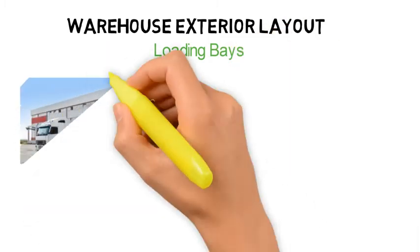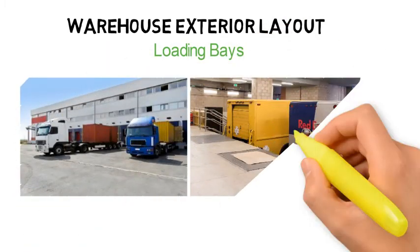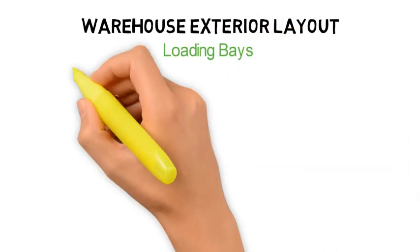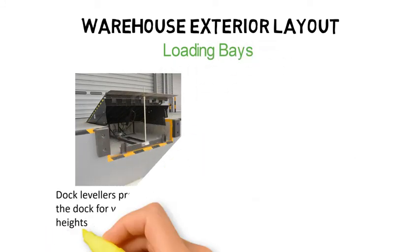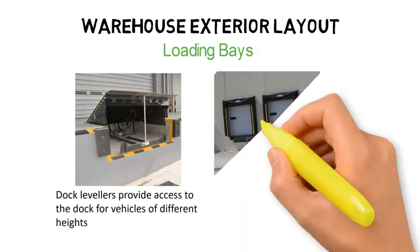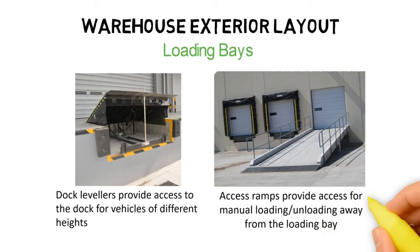To facilitate inbound and outbound activities, there must be an adequate number of loading bays for vehicles from various transportation carriers. The number of loading bays and the type of loading bays required will depend on the type of vehicles expected to be in use at the facility. In some cases, dock levelers provide flexible access for vehicles of different heights parked at the loading bay. In other cases, access ramps provide access to the dock. This is usually for vehicles which are either too small or too large to dock at the loading bay and need to do manual loading or unloading away from the loading bay.